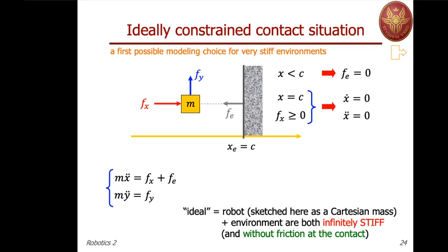So we will switch from a positive velocity x dot 0 minus to a negative velocity x dot plus immediately after the impact, which is strictly less, let's say by a factor beta less than 1, than the velocity that we had before the impact.